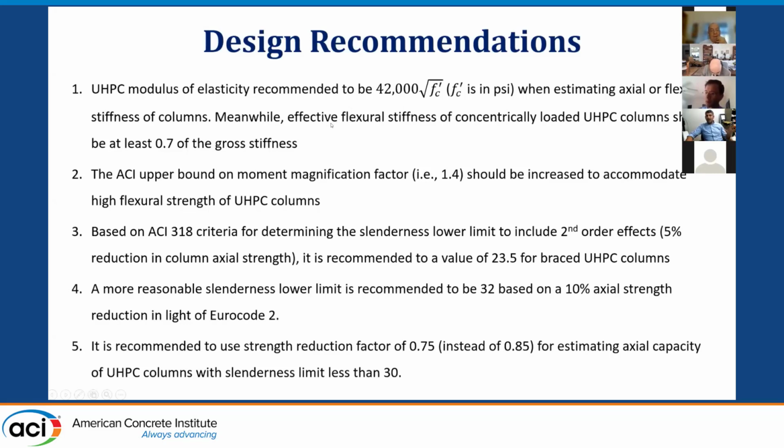That's one thing. And if we were to have an effective flexural strength for concentrically loaded UHPC columns, and this is actually for even flexural columns, not necessarily concentrically loaded. Concentric loading in this case, because we applied this for the moment magnification method, but we find that this recommendation is valid even for pure lateral load only and flexure columns, which is 0.7 of the gross stiffness. So that's one recommendation we have.